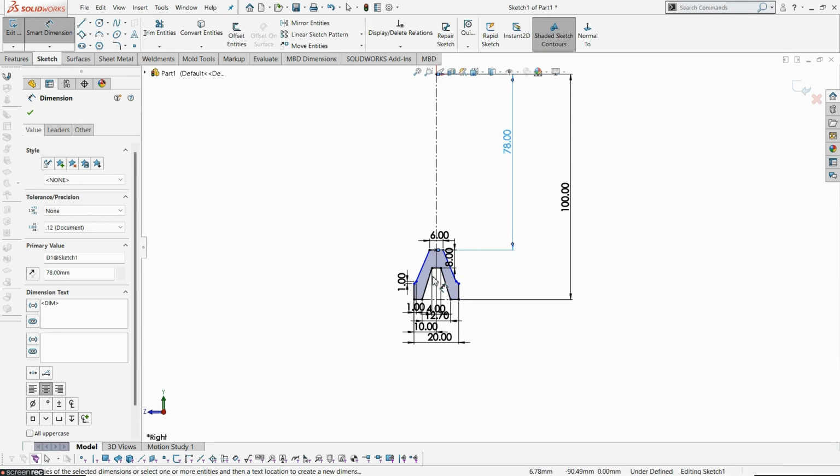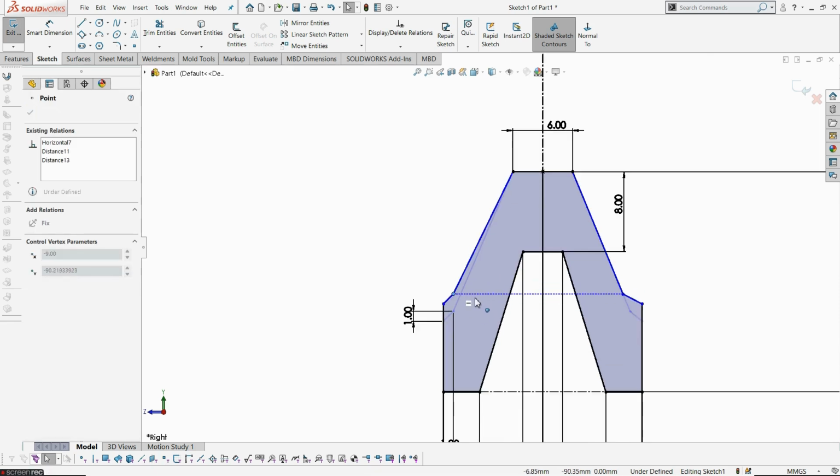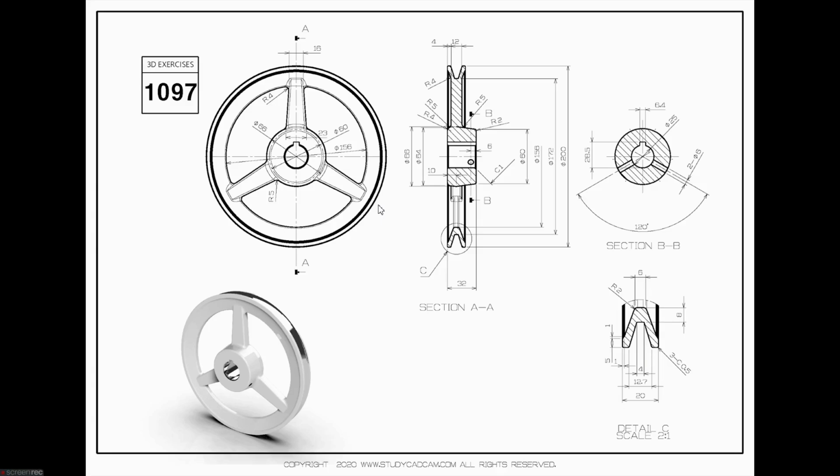If we want to fix our 2D sketch, only two things we need to do. The first thing is positioning the sketch with the origin, based on the origin. The second thing we need to do is arrest the profile with the recommended dimensions.